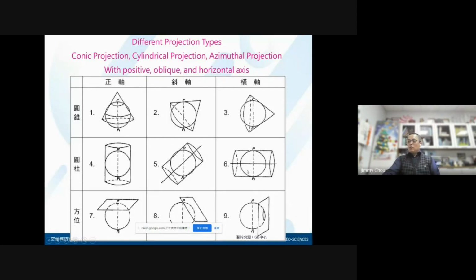So in Taiwan, we use the transverse Mercator 2 degree. Each 2 degrees, it separates the meridian, with 1 degree on each side. That's the area where we identify Taiwan, about here. Taiwan is about 2 degrees from west to east, so we use the transverse Mercator 2 degree as our data.